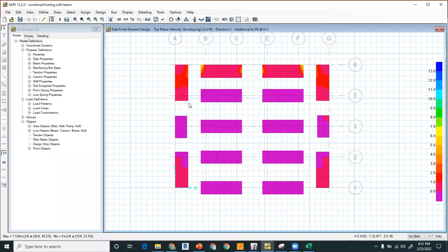and you can design any type of combined footing as per your requirement for 2-story, 3-story buildings. And if you go above 3 stories, combined footing is not applicable, then you have to go for the strap footing, or if the soil is very loose, you may go towards the raft as well.